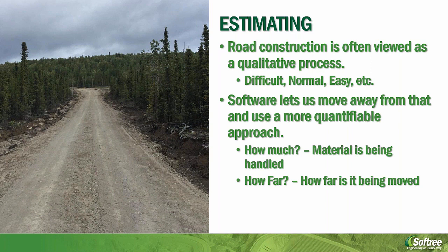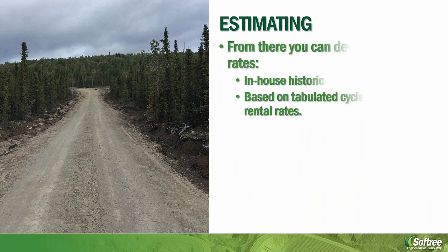The drivers for road construction costs are how much and how far. So how much material you're moving, how much material you're excavating, how much material you're using as fill, and how far you have to move that material. So the software keeps track of all that because we're comparing the two different surfaces, and you get material estimates right there, which can be useful by itself. You can also build upon that and use things like cycle times to figure out how long your crew should be there. You can also use cycle times combined with rental rates to figure out how much that's going to cost.